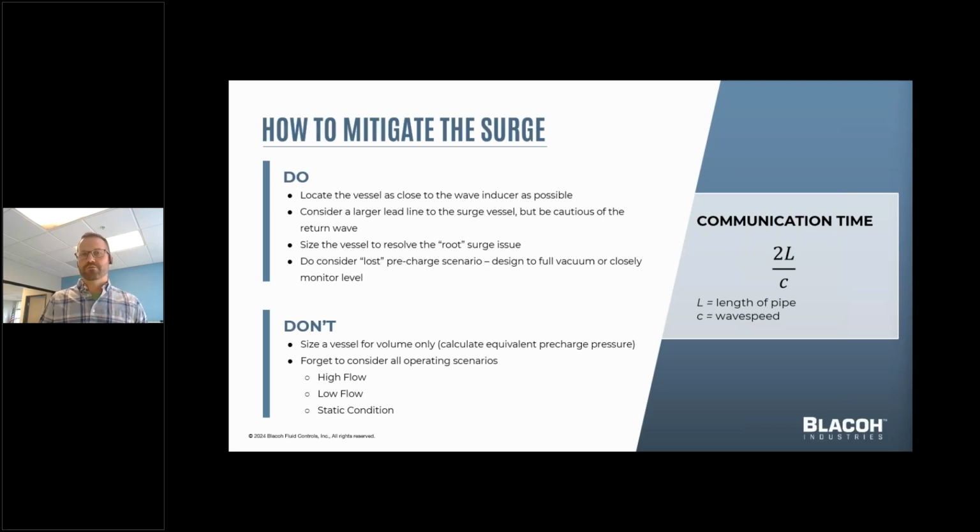Well, the same thing is true for a pumping system. It's going to see a lot of different conditions across the course of its life. It may have a rated point or a duty point that we design around for sizing the pump, but we also know it's going to operate in a wide range of conditions. We need to size the surge vessels and surge components for all of those conditions: high flow, low flow, static, vacuum conditions. All of these different things can play a role.